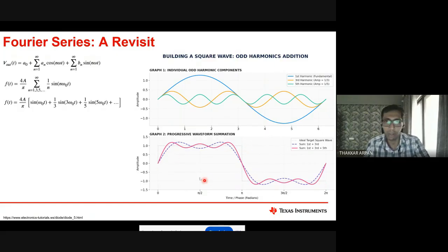So what I am trying to say is, if you have a sine wave and you manage to make a square wave, you can get higher frequencies, because this square wave has essentially the first harmonic, third harmonic, fifth harmonic, and everything. If you want the third harmonic, and you filter out all other harmonics, including the fundamental, you will get 3 times the input square wave frequency.